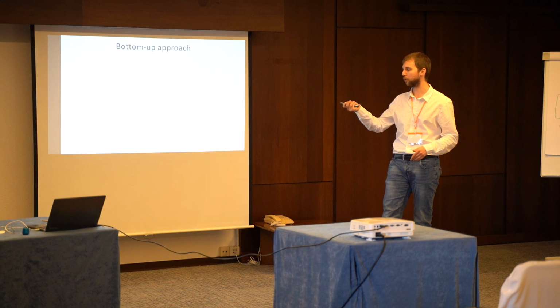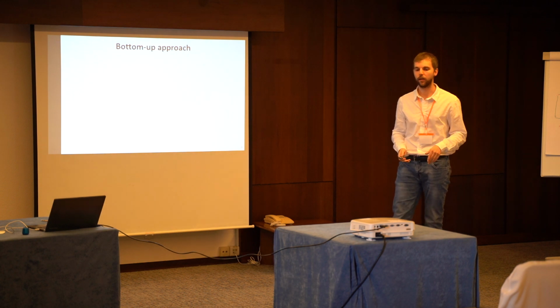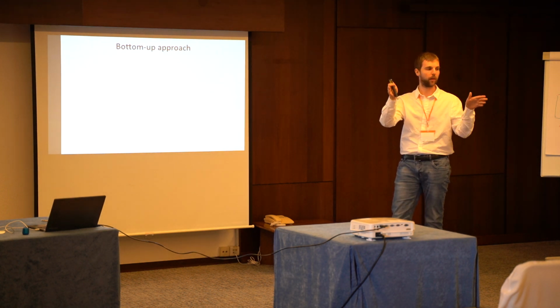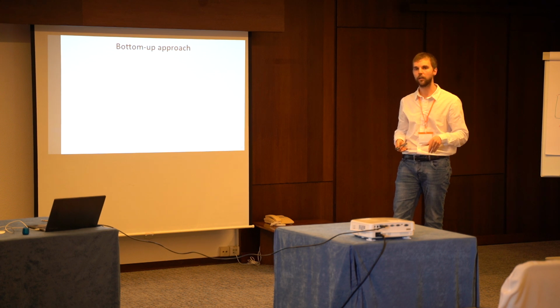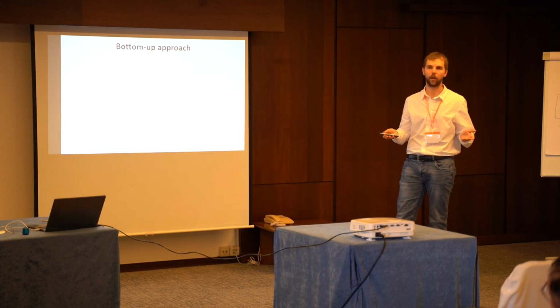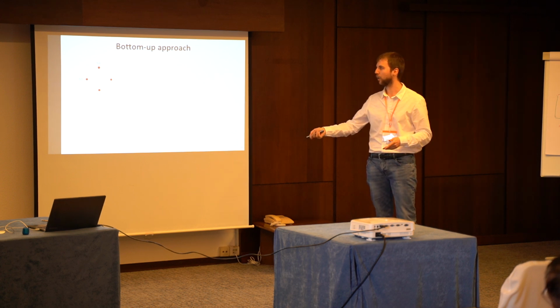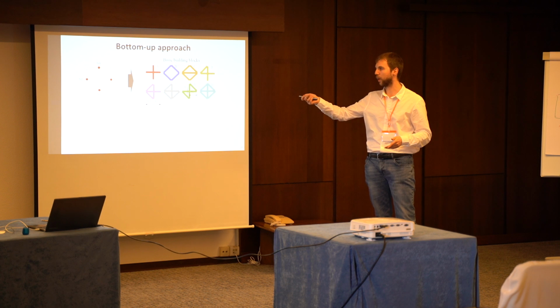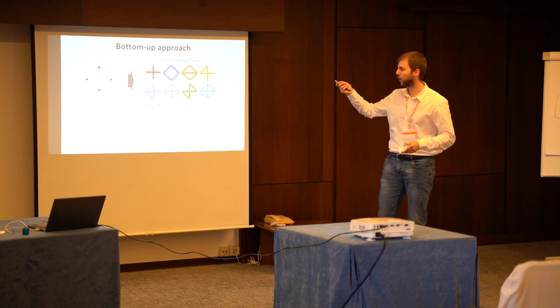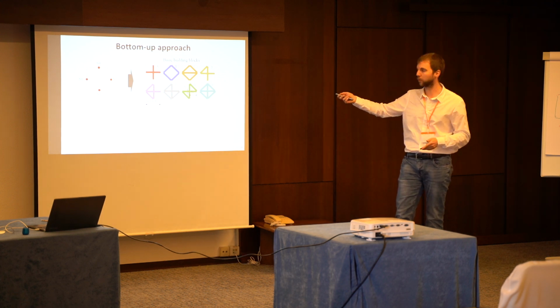We're using a bottom-up approach. Instead of starting from a pre-existing structure, for example a triangular lattice, and changing the local property to tune other properties, like wanting the macroscopic stiffness to be one specific value along one direction, we start from a simple building block, for simplicity with one node per edge, and then we connect each node to the others without leaving any node unconnected. We obtain 8 base building blocks, plus their symmetries, so reflections and rotations.